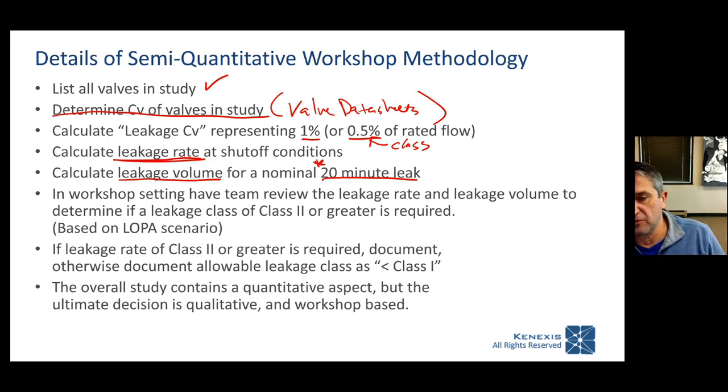So whether you want to use 10 minutes or 60 minutes, there's no standard that defines this. 20 minutes is a very common number used in QRAs, but there's no standard or rules or regulations that are going to enforce this duration. Now, at this point in time, for every valve, you'll have a quantity. So 100 liters or 10 gallons leak through this closed valve.